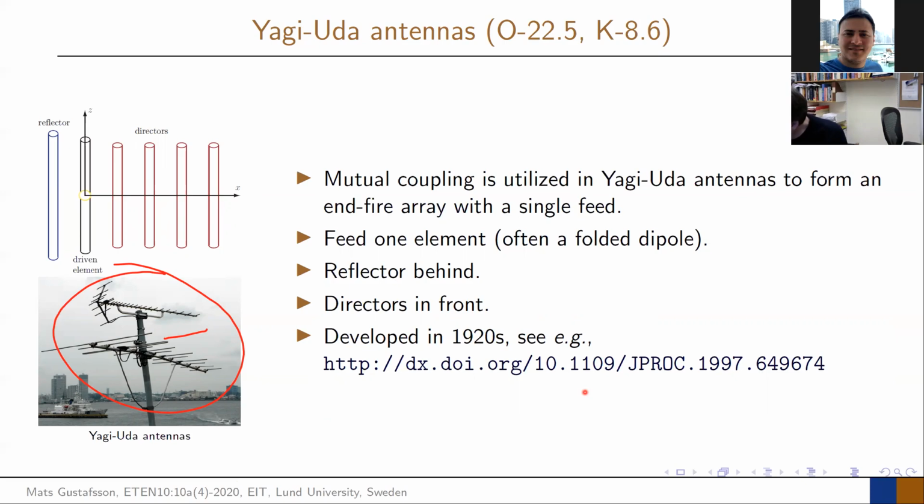And in the back of it, you can see a rather long element that sits there. In the top version, you can see a different type of element, this more V shape. It's used in many cases too. It's the same way, that's the reflector part. And then in front here, you can see many, many elements. These are pushing the radiation in these directions out here. So a fairly narrow beam is pushed in that direction by this antenna. So that is the Yagi-Uda.